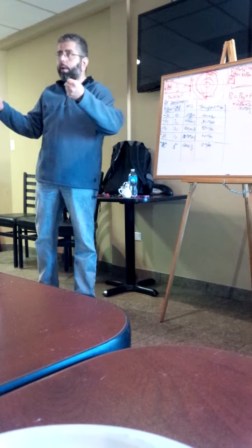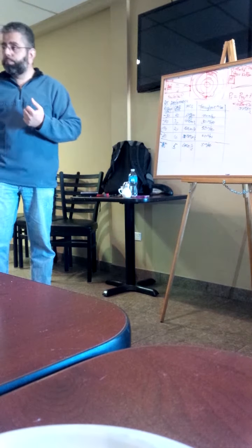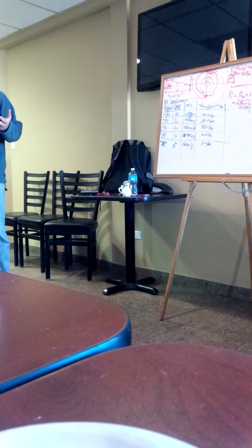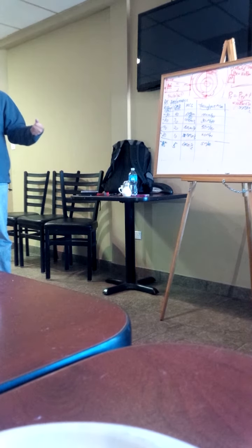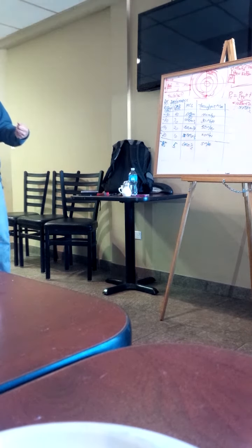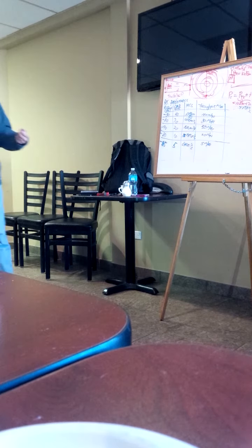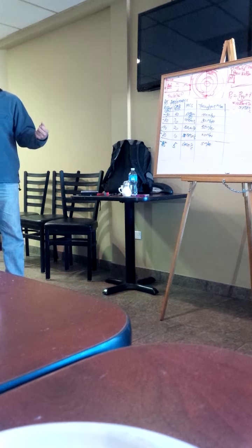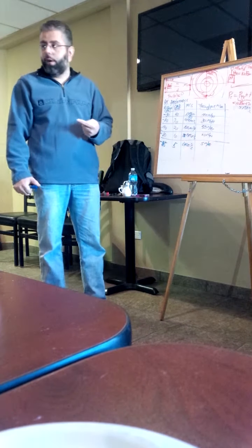And then you can go, okay, wait a minute, hey, I'm at this radio. Hey, this is Adi. Assalamu alaikum, hey man, I'm having trouble with this radio. I'm doing this link test across it. I'm doing the speed test just to verify this link. I connected up a device between one node to the other. These guys are only 100 feet apart, and I should be getting minus 50 according to my calculations, and I am. I'm getting minus 50 dBm, but when I run a speed test across it, it's only telling me he's got something like 20, 25 megabits per second. What's going on? Where I should have 100. This thing says minus 50 should give me 100, but he's only getting 25.